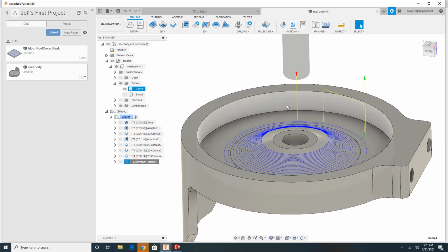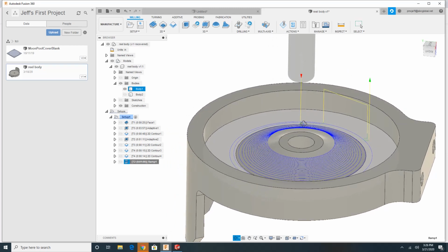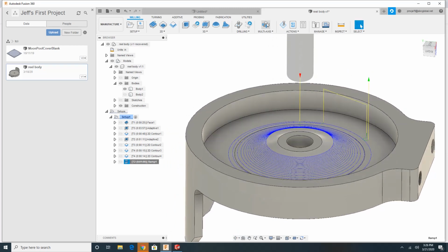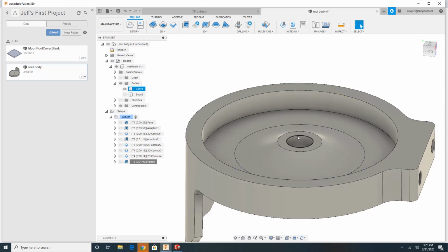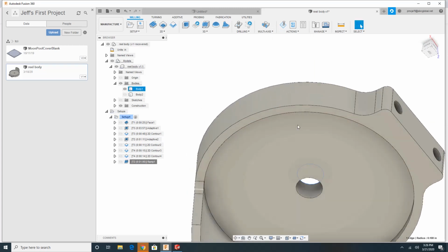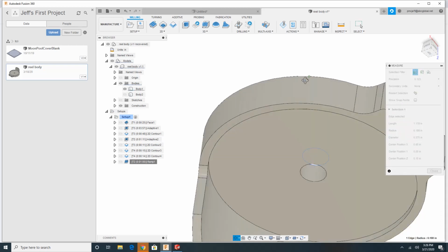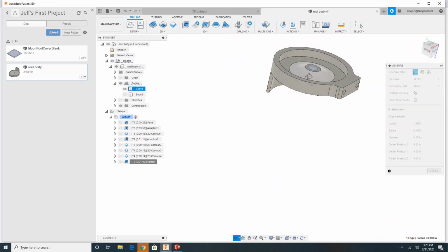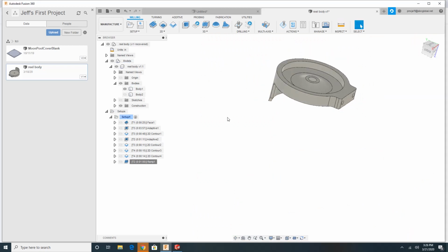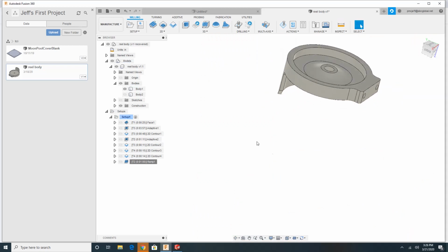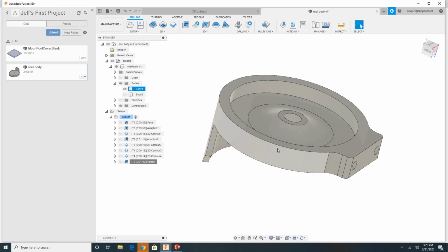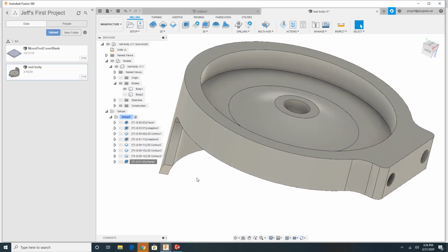So we have one more part to do on this path, and then we have to chamfer and clean up all the edges. So we've got to drill this hole. Let's just see what diameter that hole is. .375. Okay, so I'm going to give you guys a little trick. Since you only have 10 tools in the machine, and setting tools takes time, we're going to use our 1/4 inch end mill to bore that hole. So it's a 2D, it's not a drilling operation, it's a bore.